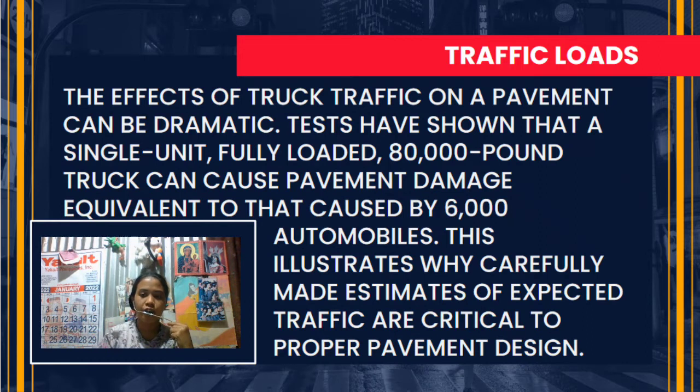Next is the effect of truck traffic on a pavement, which can be dramatic. Tests have shown that a single unit fully loaded 80,000 pound truck can cause pavement damage equivalent to that caused by 6,000 automobiles. This illustrates why carefully made estimates of expected traffic are critical to proper pavement design.